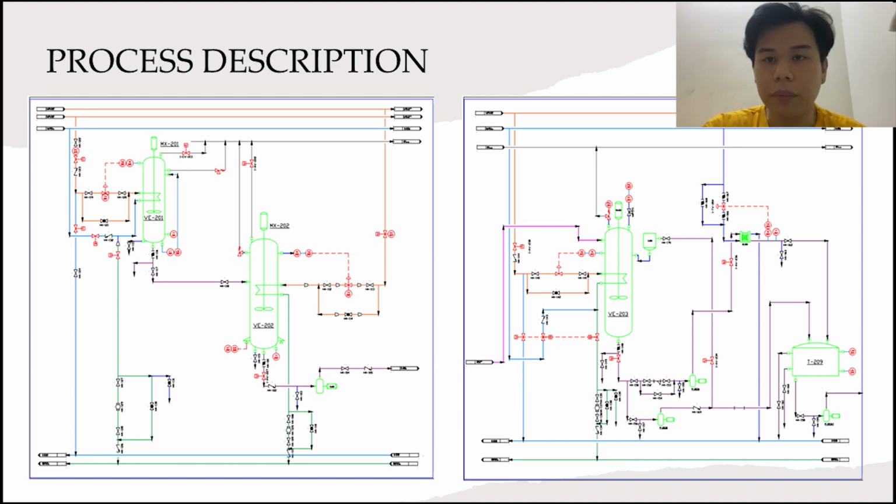Before the fluid goes from VE201 to VE202, it undergoes an esterification process, when the palm oil is converted into fatty acid alkyl esters, also known as FAAE, which are the main components of biodiesel. After that, the FAAE from VE202 is transferred to VE203, where the fluid will be heated and undergo polishing by using chemicals. The procedures are the same as transferring from VE201 to VE202.